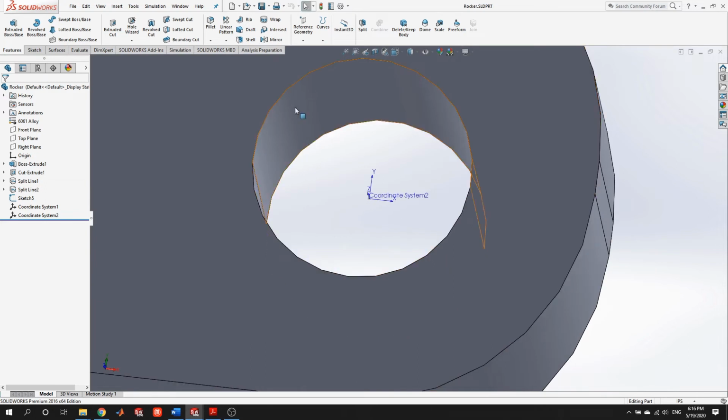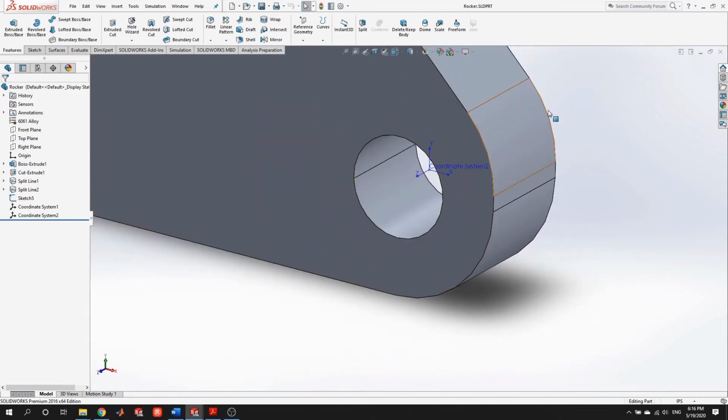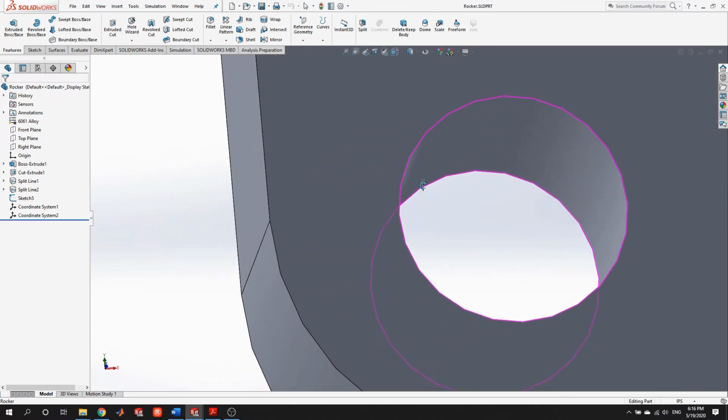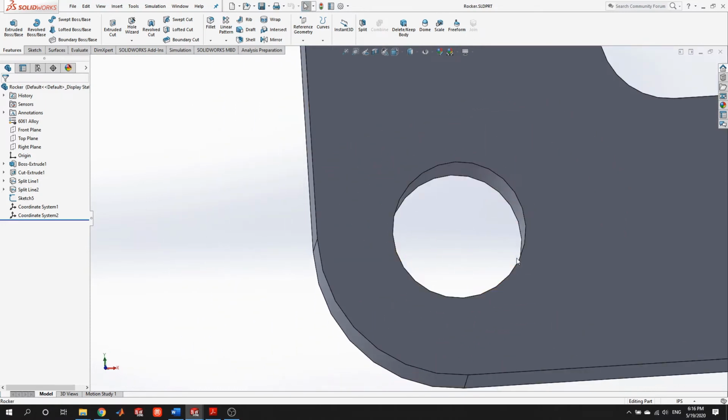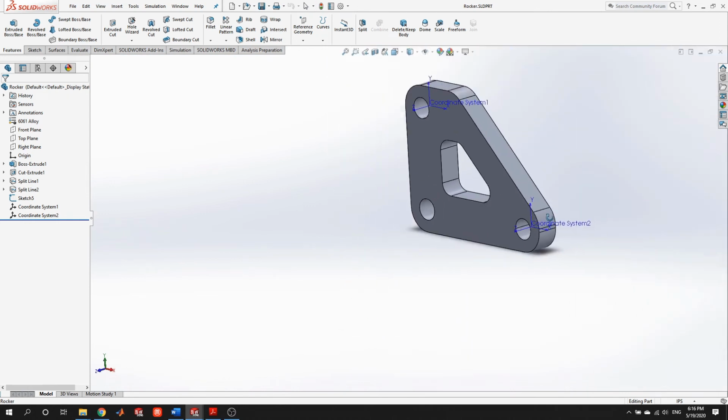I've done the same thing here to resist, basically, if there was another sort of rod through this and that it was resisting the motion by pushing up on this face. I have not done the same thing to this hole because we're going to treat this as basically an axle where this can rotate around. There's no need to split the face here.